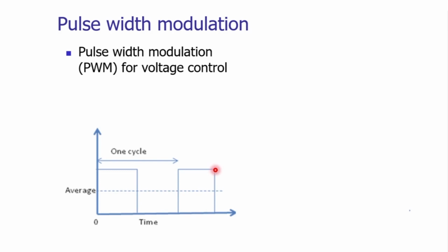But it is not essential. It may not be required to have the continuous mode of the actuation. So in this case, if we chop off, if we convert the continuous mode of application into the modulated mode or the pulse mode, we can easily reduce the average voltage application. On x-axis we are having the time, on y-axis we are having the voltage.